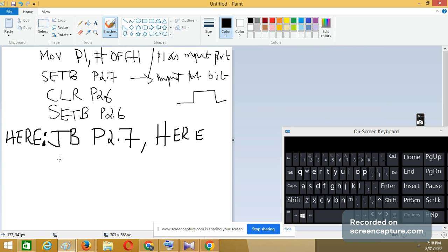So read is connected through P2.5. So it is read bar. To say that I want to read, first you have to clear P2.5 because P2.5 is connected to read bar. So it starts reading. It starts reading means P1 starts reading that digital input. The digital output of the ADC comes as digital input to the microcontroller through P1 because we have connected P1 to D. So D0 to D7 will come to P1.0 to P1.7. So it is available in P1.